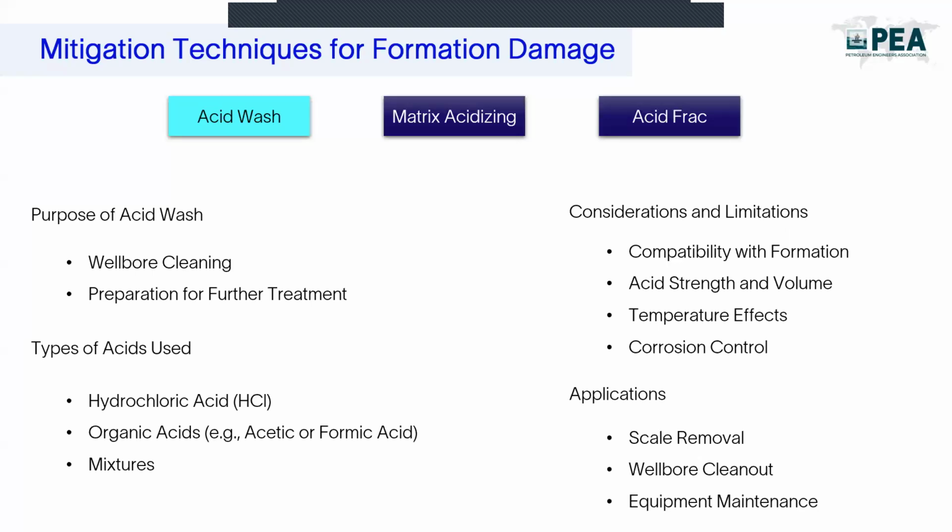The main purpose of acid wash is primarily, as I said, to clean up and remove the scale. Sometimes all you need is to clean up the deposit and the scale around the wellbore, and then all the damage is gone.